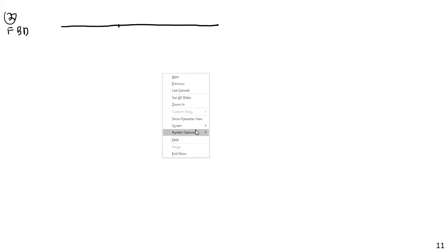Step 2 is going to be my free body diagram. And now it's just like what we've done previously with the method of sections, or sorry, with the method of inspection. So this is why I put the hinge example with the inspection rather than with integration or via method of sections, although you could, of course, use any method for it. So the first thing I'm going to do is just draw a big, unified free body diagram. The pin disappears. I am now treating this as just a single rigid body, but I could go ahead and put a pin on there. But really, I'm treating this as a single rigid body.